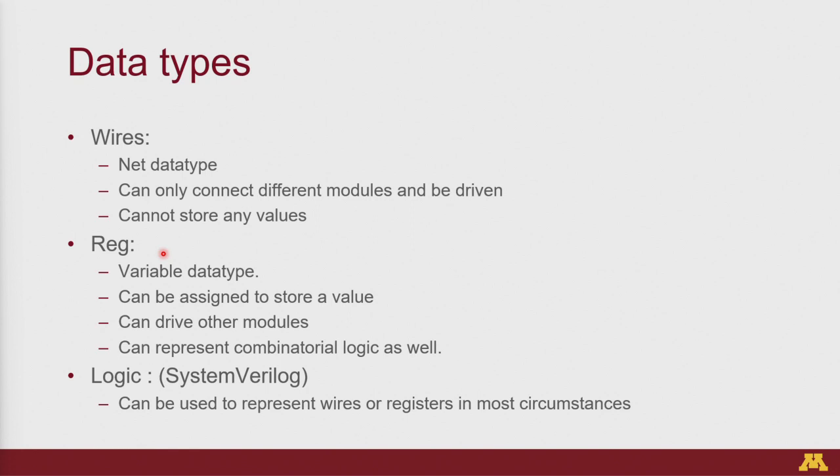Z means an unconnected wire. The way you think of it is as a high impedance, right? If you have a design but do not connect a pin to anything else, that will be like a high impedance line. So that's the Z value. This should be good enough to work with the designs you have, and logic should be a go-to for all of this.